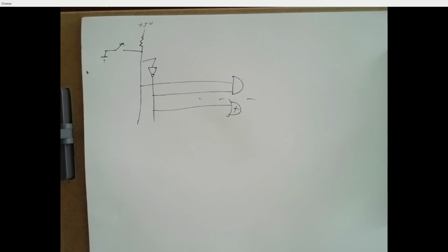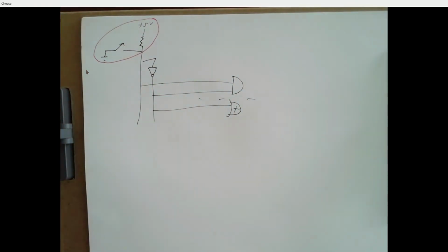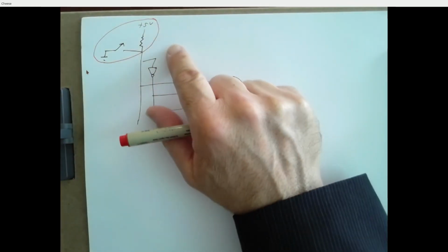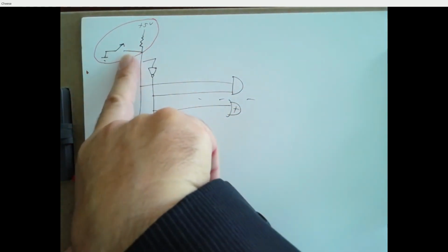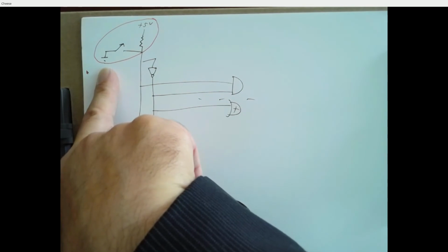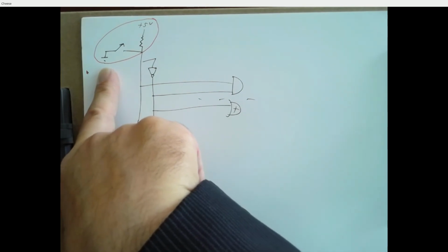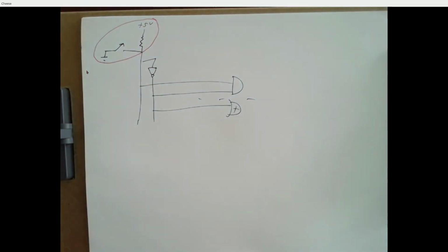So this part up here where you're making a switch, you have to have a resistor going up to 5 volts. You have to label that 5 volts VCC. You have to have a switch connecting here and pulling you down to ground. I don't think I've seen any incorrectly wired switches, but I've seen a few where these pieces are missing. So make sure you've got all those pieces in there.